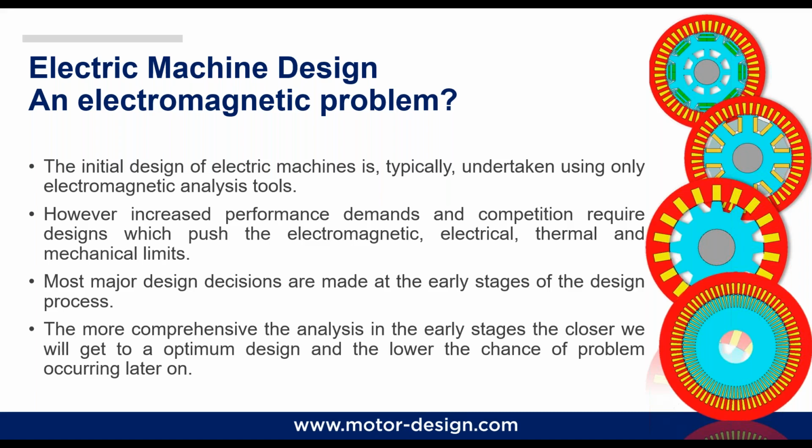So basically, this allows us to make correct decisions and create very competitive designs that have a much lower chance of problems occurring later on. So we don't want a process where we start the electromagnetic design, optimize the electromagnetic design, and then find that it, for example, gets too hot in the winding, or the magnets get too hot, or that it is mechanically not strong enough, or there are other bits of behavior that we didn't consider during the early stages of the design process.